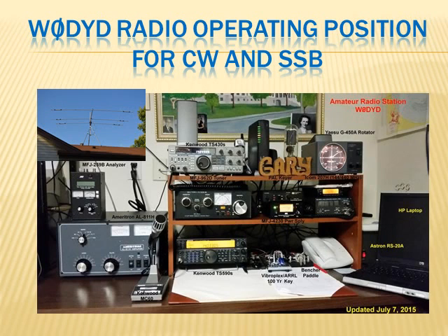And you can see the layout here with the TS590S lower center. Right above that is an MFJ tuner, which I use with the Ameritron amplifier, the AL811H. However, when I'm operating remote, since I don't have really good control on the amplifier, and it needs tuning as you change frequencies, I simply put the switch on the MFJ tuner in the bypass position and just use the automatic antenna tuner in the TS590S, which I can control from the remote location.